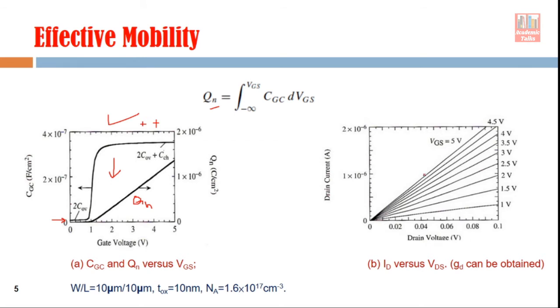And in this graph you can see drain current plotted versus drain voltage. This is VDS actually, right? ID versus VDS, and this is for low VDS. You see here it is up to 0.1 volt. If we applied higher voltage, then definitely we would get the saturation region, but we are confining ourselves to the low VDS range, right? You see here the graph is almost linear.